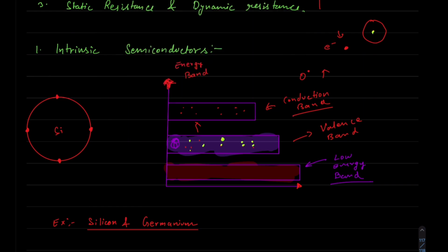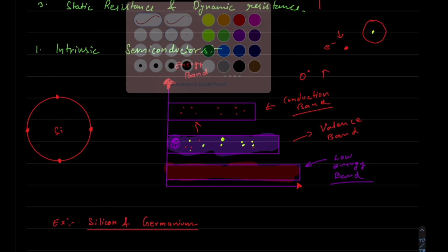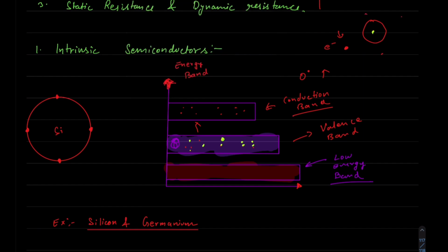So why is that significant? Let's say a lot of other electrons are around this hole. What can happen is these electrons can take the other electron's initial place because they're in the same valence band. Now, if they've taken its place, they leave a vacancy in their initial position. So we can say the hole has traveled from here to here. And then another electron can take that position, and we can say the hole has then traveled from here. And that's the concept of holes and electrons.